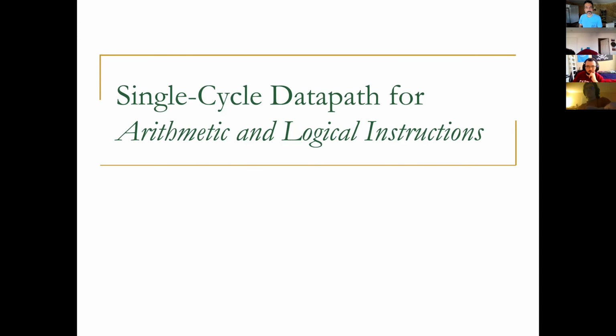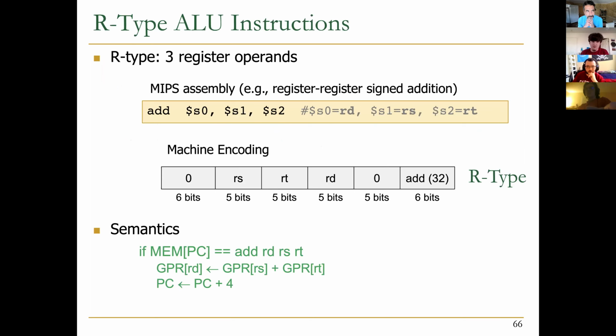Okay, so let's jump into the interesting part of this. We start with R-type ALU instructions. These are essential, important types of instructions, one category out of a few others, of MIPS instructions or general assembly instructions. Hopefully you remember what I'm talking about. Beyond R-type, we have I-type, and we have memory access and data movement types. So we have different types of instructions. We start constructing this single-cycle microarchitecture for MIPS with R-type, and then we add more types of instruction as we move forward.